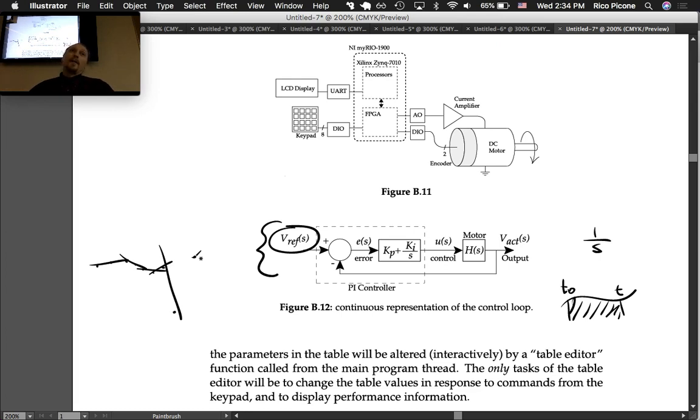One thing that happens a lot with this is that you'll see jitter. It'll go back and forth rapidly, because it'll push it. Say you're too far right, it'll push it left, and then you're too far left, so it pushes it right, and then it just goes back and forth rapidly. That is the problem with derivative. Not that we shouldn't use it, because derivative can be very helpful, but we have to be more careful with it. It's very safe to leave derivative out and just say integral, it grows over time.